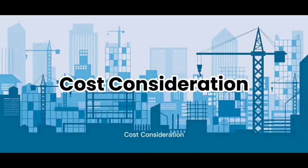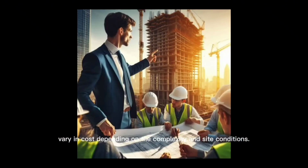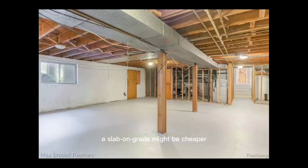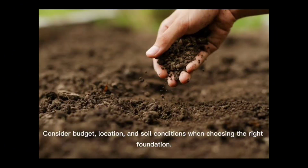Cost consideration. Footing and foundation types vary in cost depending on the complexity and site conditions. For example, a slab-on-grade might be cheaper than a full basement foundation but offers less space. Consider budget, location, and soil conditions when choosing the right foundation.